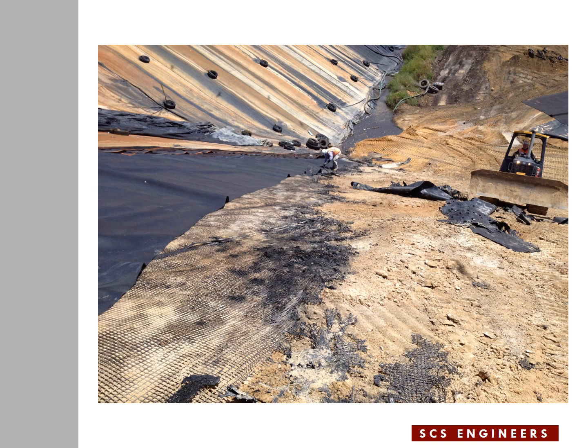As you see here, they are cutting the excess material in order to create a new edge for the geomembrane. The geomembrane that you see in this slide is the original geomembrane that was not impacted during the fire event. Geogrid is below the geomembrane, is visible. Parts of it are, the burnt pieces are still there, that's being handled. They're going to cut back the geogrid also to the line of cut in the geomembrane, in order to prepare the area for repair.